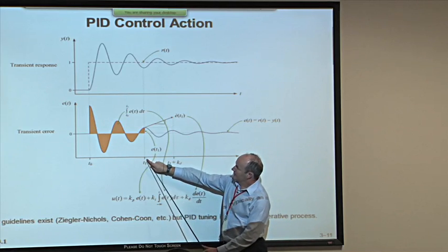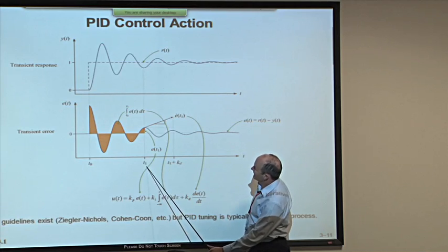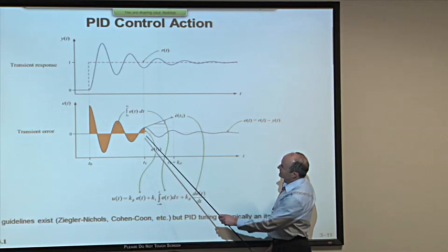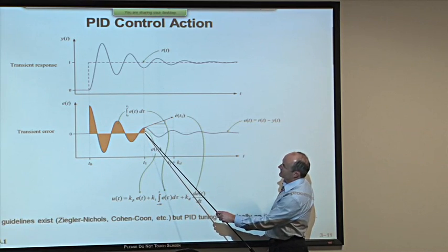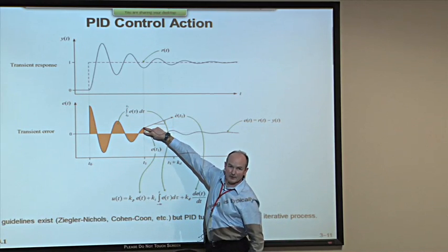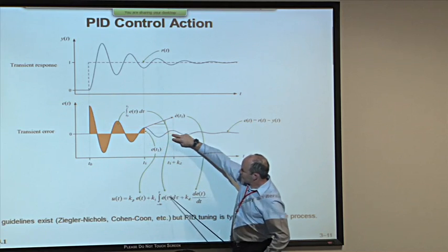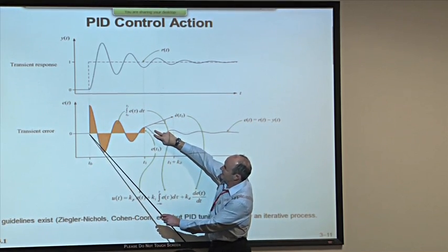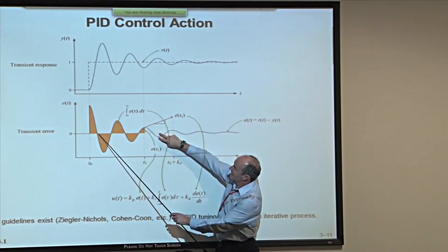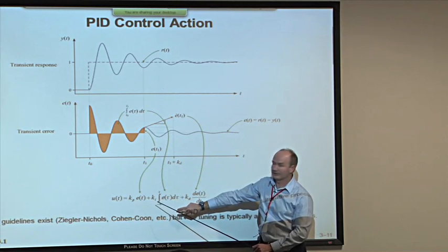And we might want to know at some time, call it t1, what the output of the controller will be. So the output of the controller at time t1, I suppose it should be u of t1, is equal to kp times the instantaneous error. That's the first term there. Whatever the error happens to be at that time, multiplied by the proportional gain, that's what you get there. The integral term, well, that's the integral of the error, strictly over all time, but here from time t equals 0 to t1. That orange area multiplied by the integral gain, that's what the integral term involves.